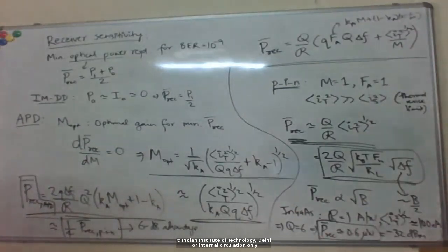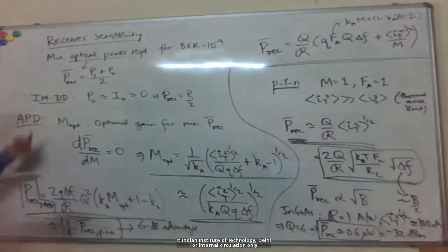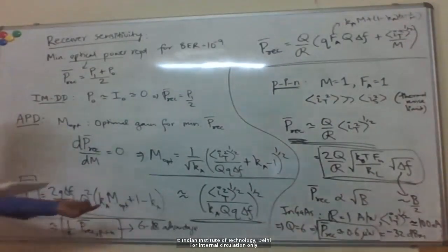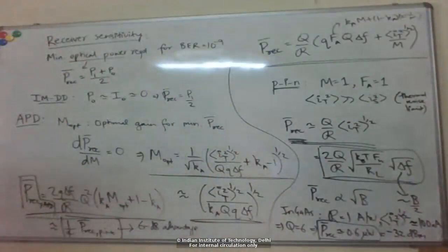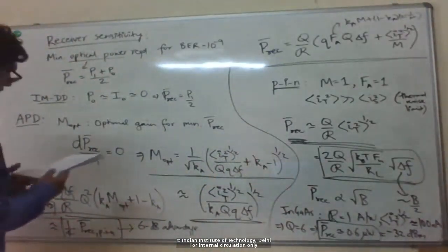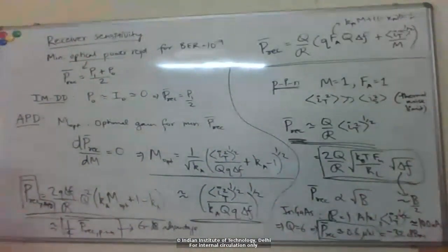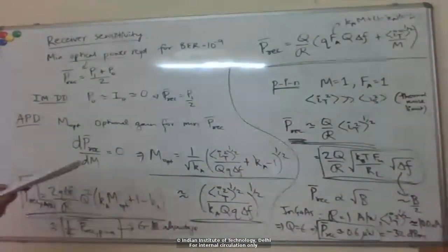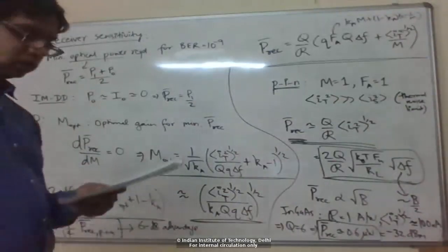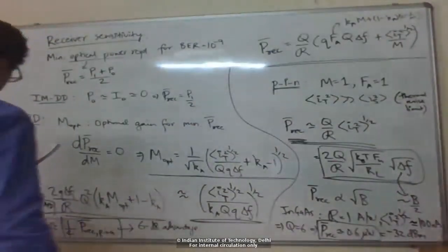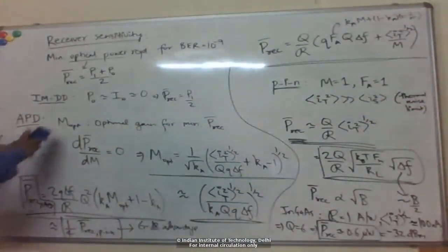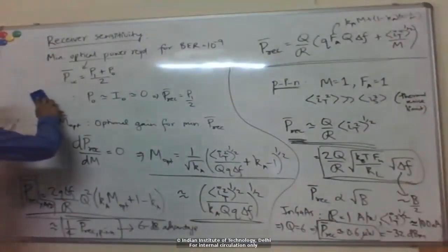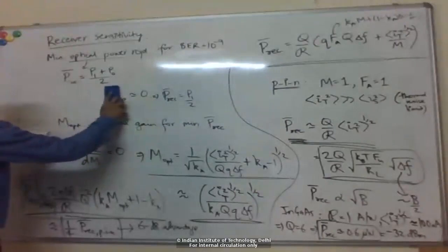Sometimes we also measure the receiver sensitivity not in terms of optical power, in microwatts or dBm, but in terms of, for example, the SNR that we discussed last time, or the number of photons per bit. So we just briefly look at that.